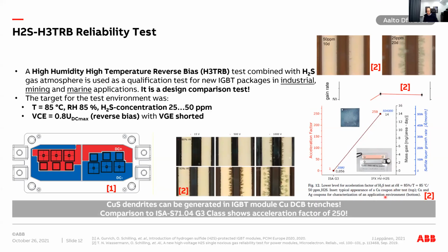But will it tell us the whole story? Because these are always bare metal plates. So how about the situation inside the silicon gel of the component? Because there surely has to be some kind of a time constant for the gases and the moisture to penetrate. We know that for the moisture, it is typically less than 2 days, but for the gases, is it the same, especially in high humidity?